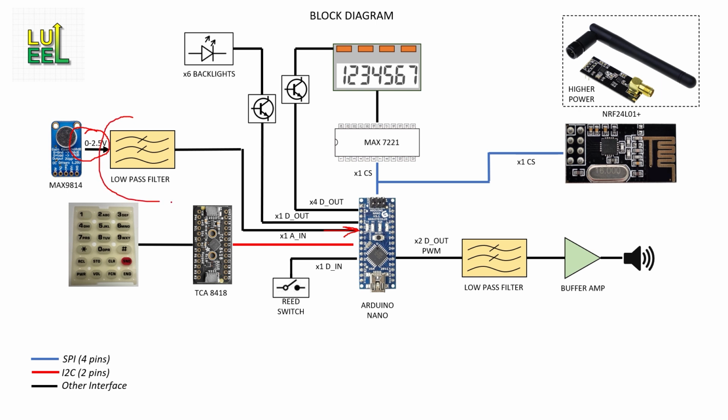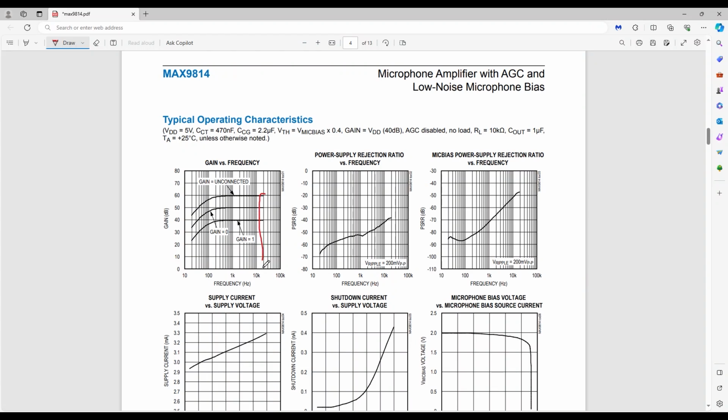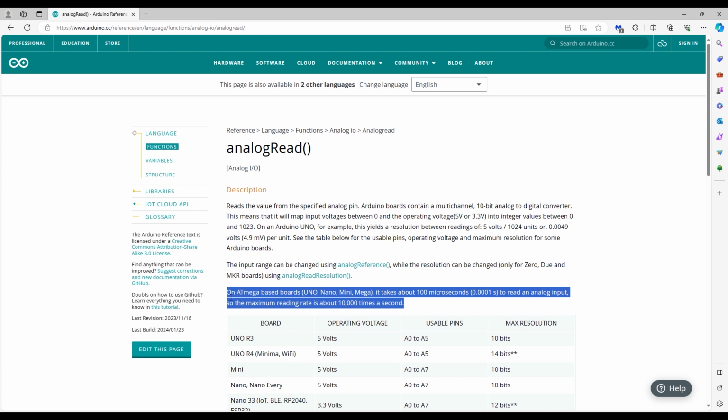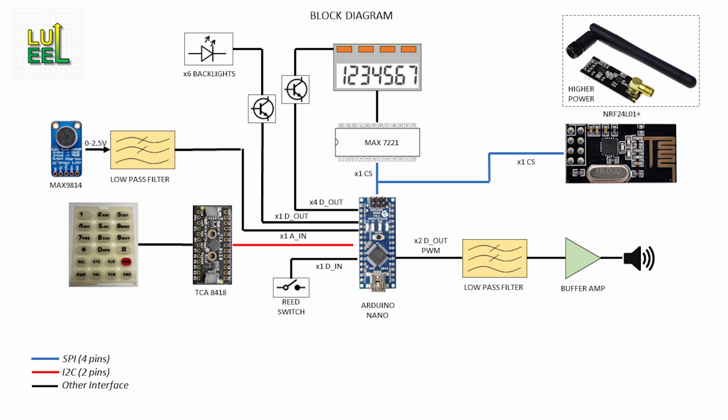The final element that I need in this section is a low-pass filter. The bandwidth of the MAX9814 is 20 kHz, which is much more than I need. For basic voice communication, around 3 to 4 kHz is plenty. But the bigger issue is the sampling rate of the ADC. Now, I haven't settled on one yet, but I know it's not going to be anywhere near 40 kHz, which is the absolute minimum needed to avoid aliasing issues. And once a signal is badly aliased, there's nothing you can do downstream to fix it. So I gotta have that low-pass filter in there.